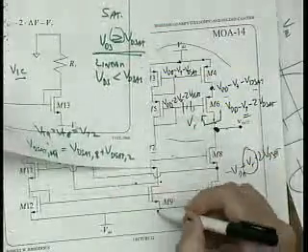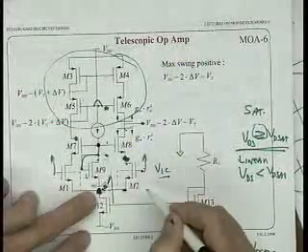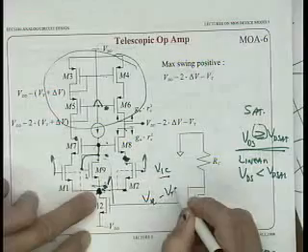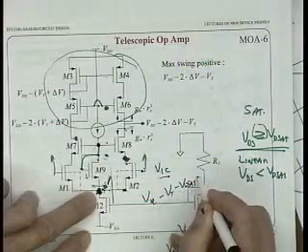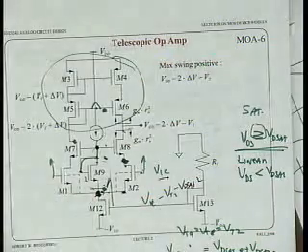This is relative to minus VDD. This one is relative to the voltage on the source of M2, which is actually V input common minus VT minus VDSAT of 2. Right? Yes.